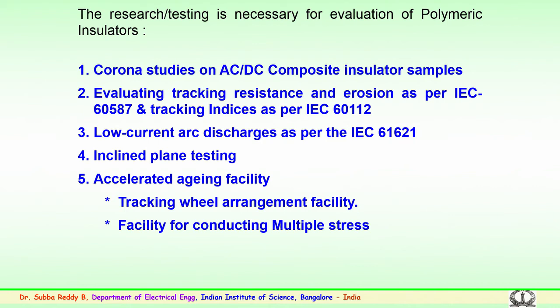The other important aspect, the reliability verification for the polymer full scale insulators, or full-fledged insulator or a prorated type of insulator, is the accelerated aging experimentation. Accelerated aging experimentation again consists of 2 to 3 experiments which are normally carried out in the laboratory. Basically, there is a salt fog experimentation, which could be carried out for a 1000 hours period.